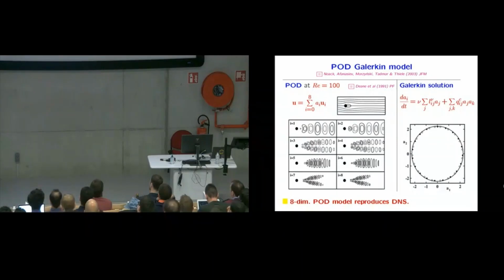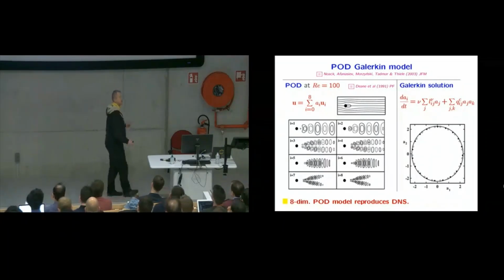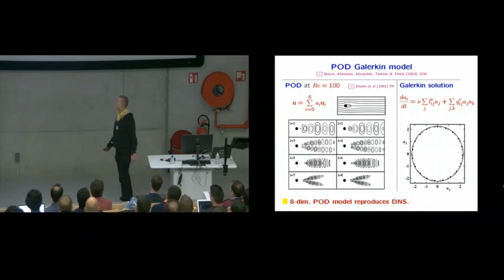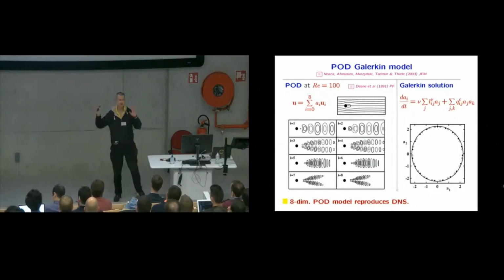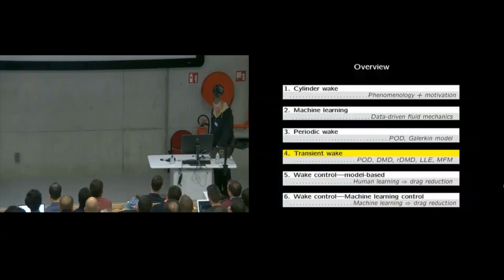But you change the viscosity a bit, you change the Reynolds number from 100 to 80, and you get to the fixed point. You change it from 100 to 120, and it explodes. You look at the transient, and the transient is 20 times longer than the real transient. You look at this point here, and it's a mean flow, not the steady solution. So we are a bit in trouble. We have a beautiful model, but it has a very narrow range of validity.